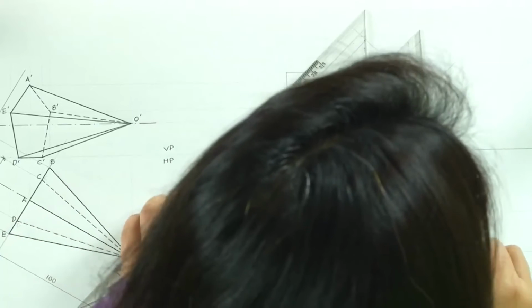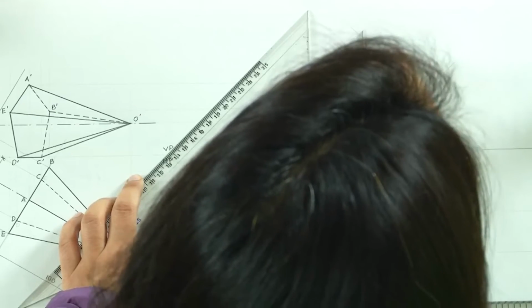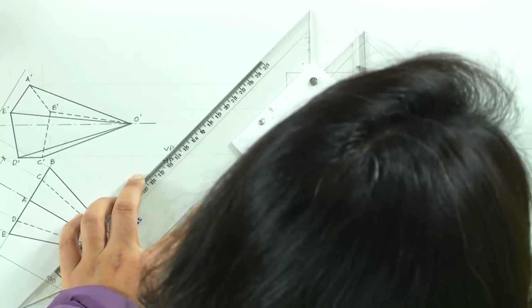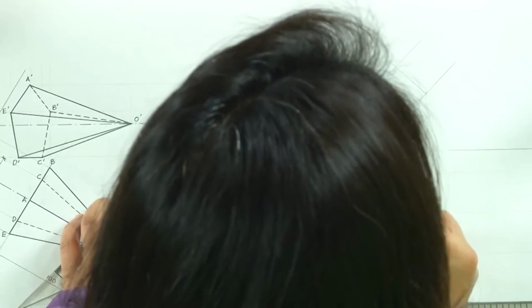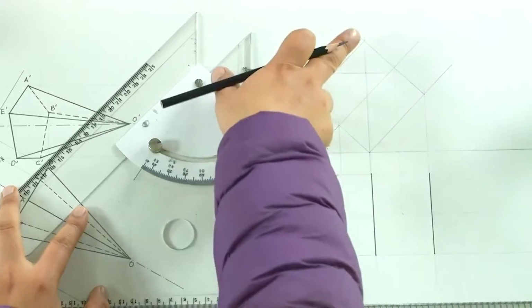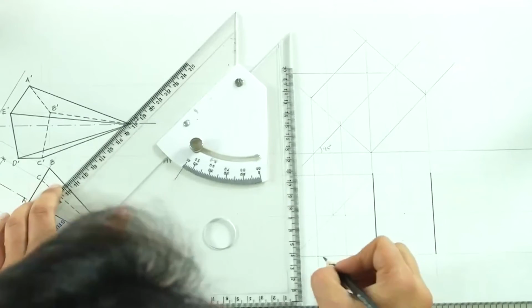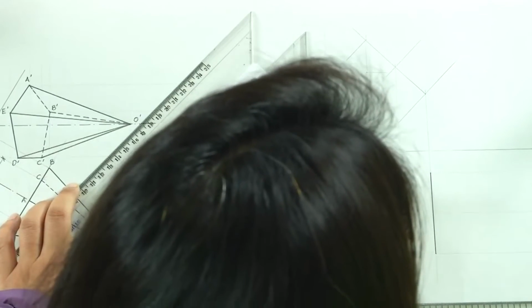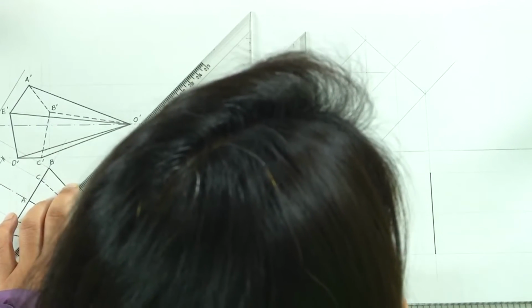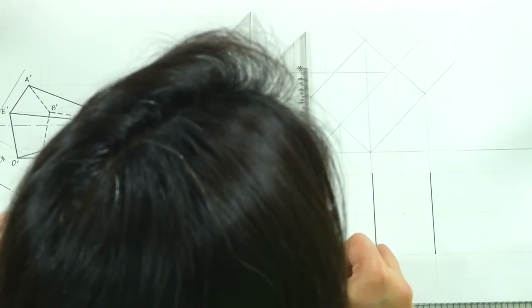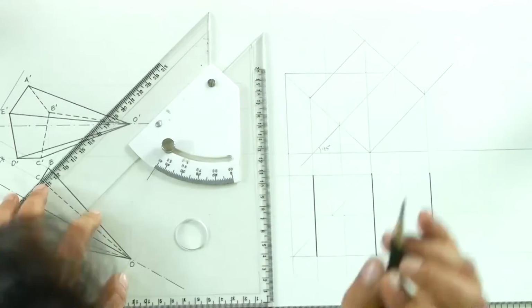So I'm seeing it from the top, and when I see it from the top, I see this edge here. I see both these edges right on top of each other. So I see one single edge here representing both, but I'm darkening it because I'm seeing this edge first, so it's a solid line, and the hidden line will actually be hidden behind the solid line. And then I see the solid edge, which is this.